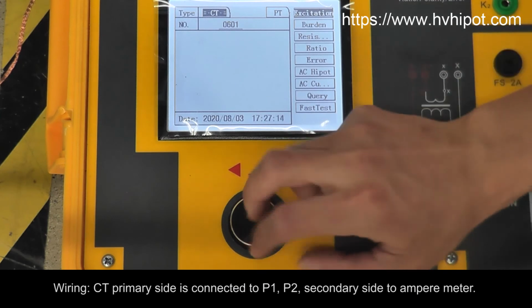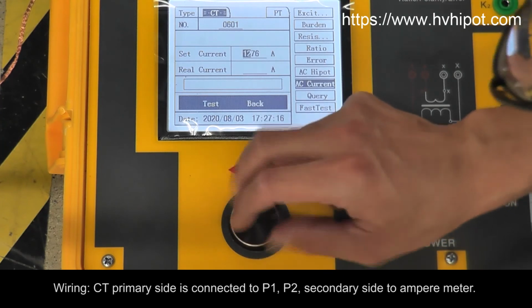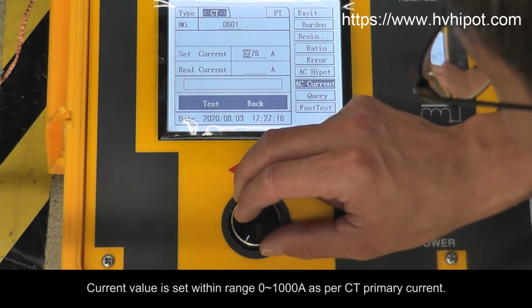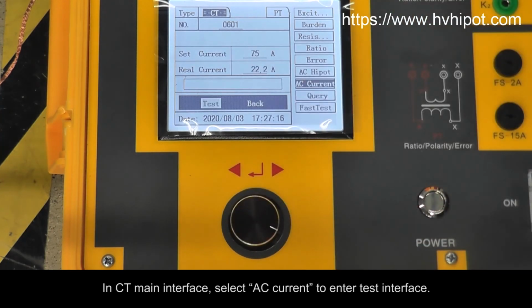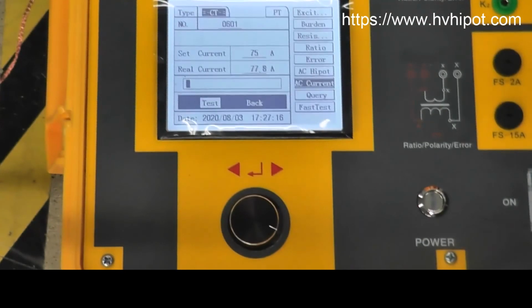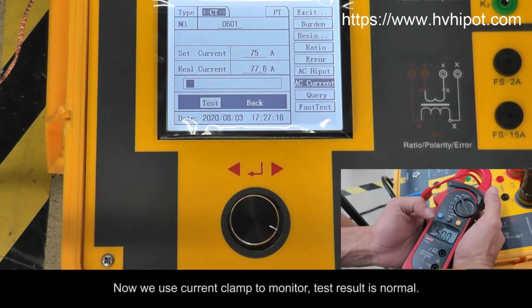Wiring. CT primary side is connected to P1, P2, secondary side ampere meter. Current value is set within range 0 to approximately 1000 A as per CT primary current. In CT main interface, select AC current to enter test interface. After setting AC current, turn on power switch. Select test, press controller to start testing. Now we use current clamp to monitor, test result is normal.